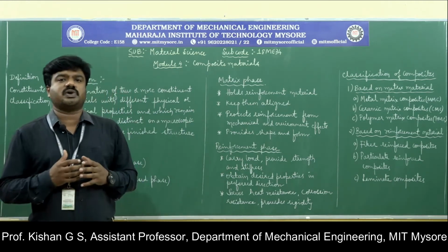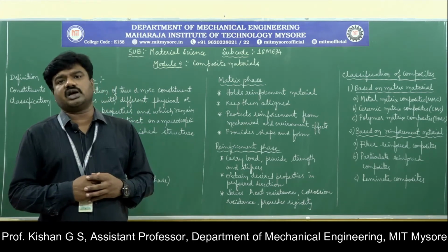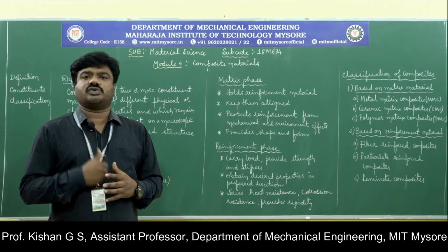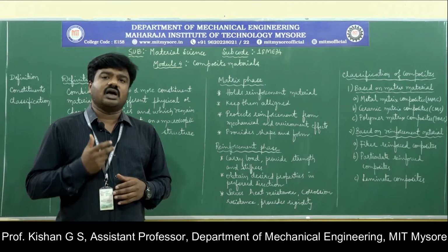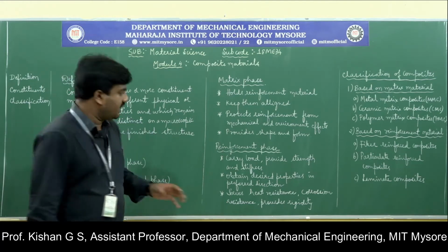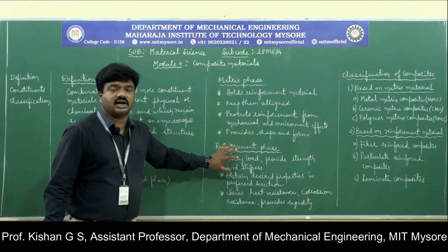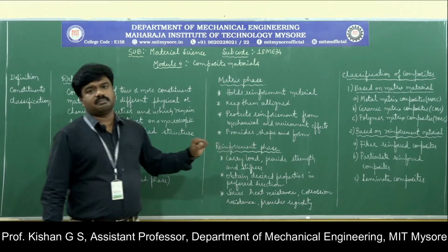So the reinforcement phase carries the load applied on the material. Whatever the type of load, it may be tensile load, impact load, or any kind of load applied on the composite specimen, it is the reinforcement phase that takes the load and results in the strength and stiffness of the material.